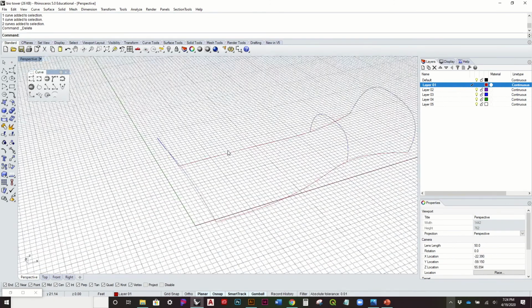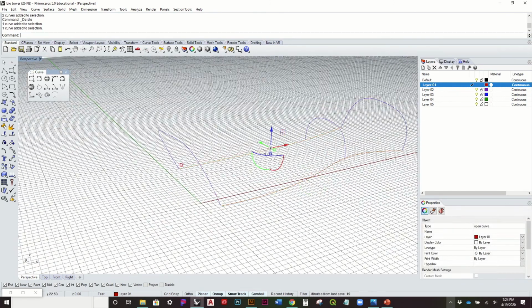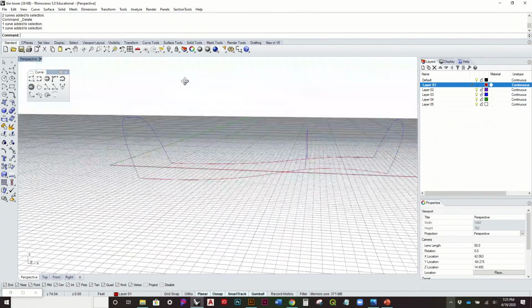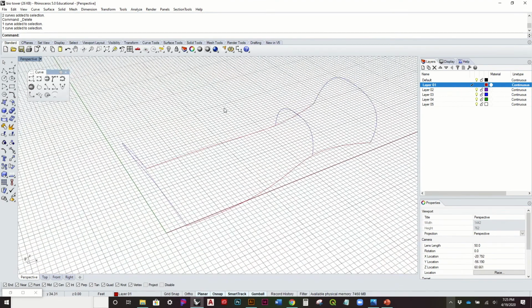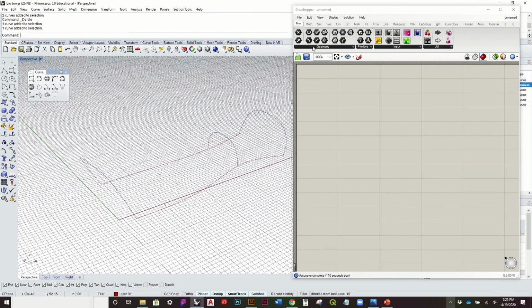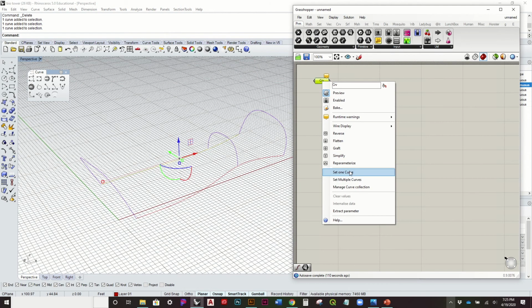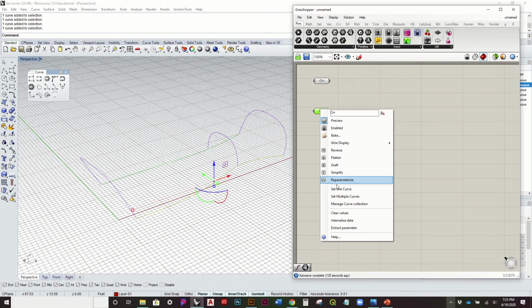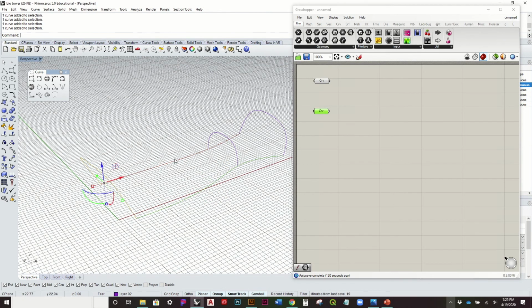When you're creating the actual thing in the script, you'll have to do some organization of it, because it's sometimes a little counterintuitive to what you might think. So like I said, we'll go ahead and get started with this. We want to use the Sweep2, so I'm going to reference one curve, copy and paste and reference the next one, and then reference my three cross sections. Like I said, it's one of those things where it's a little counterintuitive.